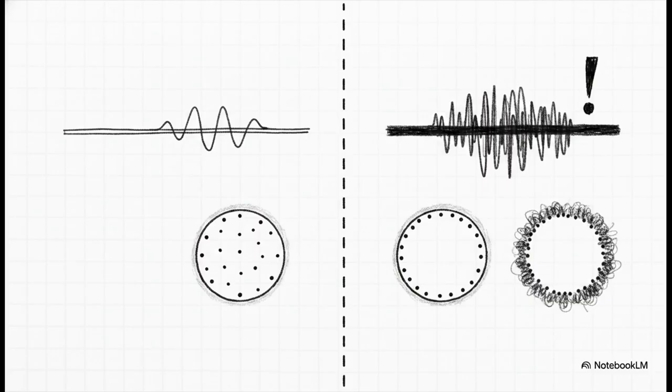Luckily, engineers have precise mathematical thresholds where they can just safely ignore this crowding effect. The skin effect is considered totally negligible when the supply frequency is relatively low, so under 50 Hertz, and when the conductor diameter is small, specifically under 1 centimeter. But when we're talking about those massive grid lines, it's a major factor they absolutely have to manage.